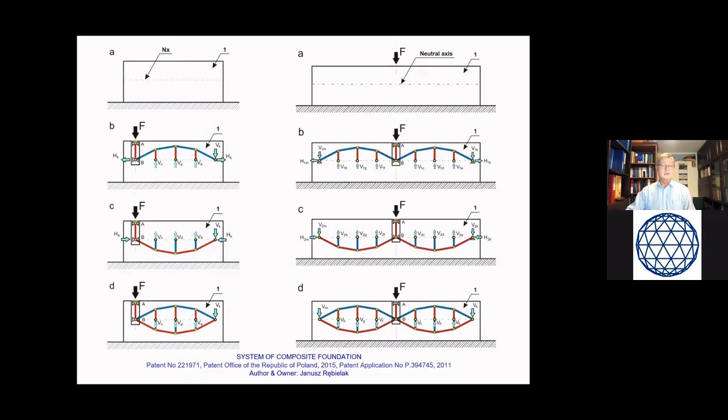Outer force is transmitted via short vertical members and by means of the intermediate system to the structural nodes. The intermediate system is built of two subsystems. The first one is called a funicular system, and it is located below the neutral axis, while the second one is called an arch system, and it is placed above the neutral axis of these beams.